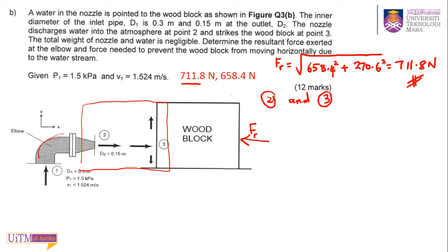Okay, and you have your V2 going out, and you have your P2A2 which is 0. And you have V3 coming in here, but this is also zero. Okay, then you write your linear momentum equation in x direction.